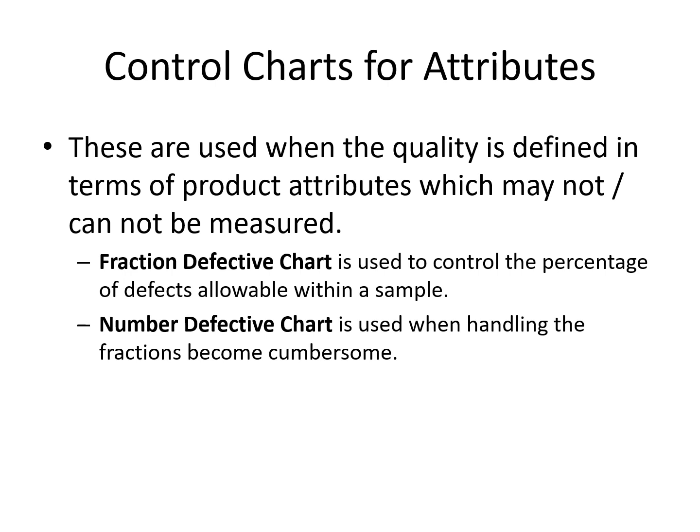So wherever there is mass production going on, or a larger number of production happening, we use either the fraction defective or the number defective, based on the number of defective pieces that we are getting within a sample. If the number of defective pieces within a sample is significantly large, one tends to use the fraction defective chart. If they are not so large, then instead of fractions, we use the actual numbers of how many defects there are, whether acceptable or not based on the process.